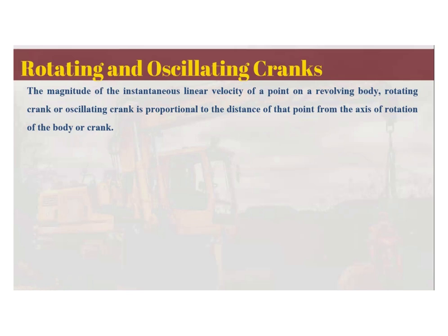Some of you, during your topic number 3 laboratory plate, asked: is there a velocity for an oscillating crank even if it is not rotating fully? The answer is yes. Basically, the linear velocity is proportional to the distance of the point on that crank from the axis of rotation.